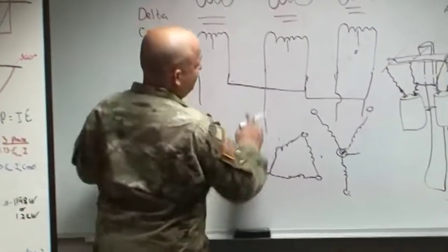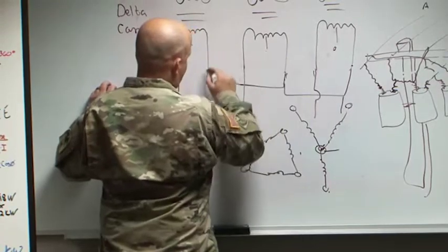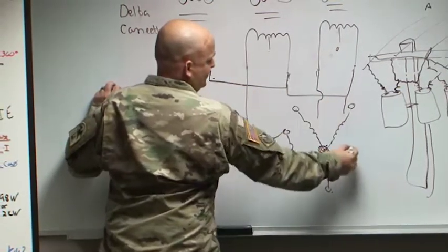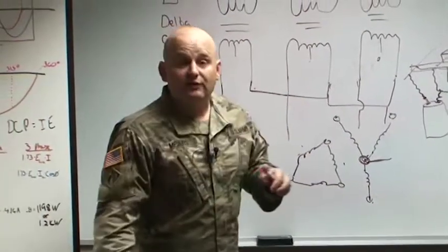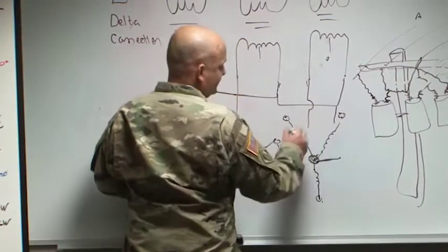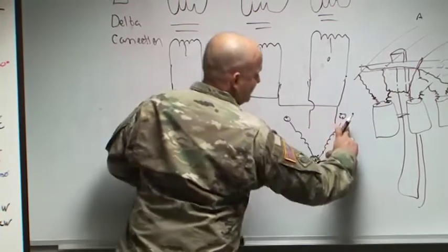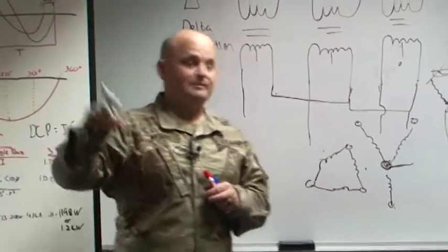Now I'm looking at this secondary side. We call this A, B, and C. And each one of them in this same point came down, and they connected to that same neutral point, and they still have their same independent outer values there. So now, back to the vector math, if I take a reference from here to here for voltage, so from this point to any one of these, I'm going to be measuring the magnitude of one of these vectors at whatever respective phase angle it's at.